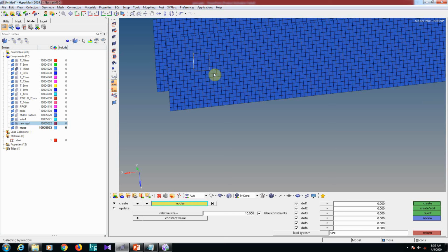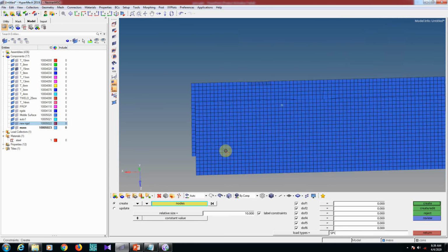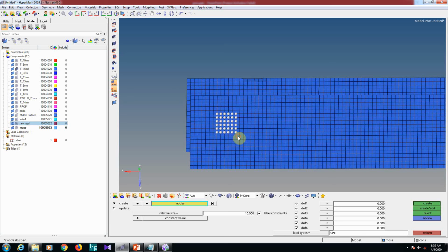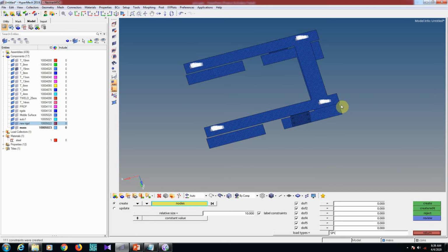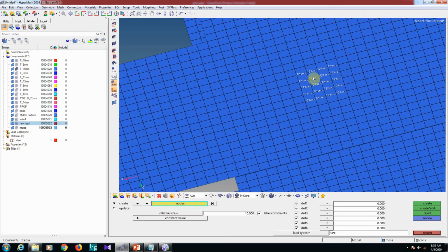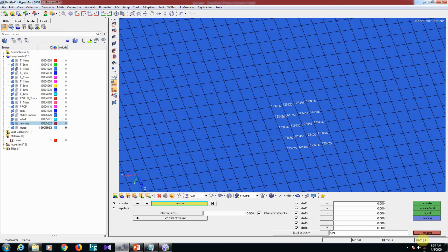The main learning over here is how we are setting up, what cards we are using, and we need to understand the purpose of it. Wherever the opposite side is selected, you can deselect these. All degrees of freedom are fixed. Now you can see this is 1 2 3 4 5 6, all degrees of freedom are fixed.